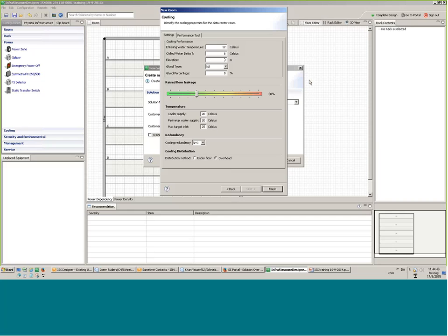So they get derated. It's information to us. The tool itself is not taking care of it. So please tell us it is 1,000 meters or Johannesburg 1,700 or wherever. Glycol type as well. What you have is also derating the water capacity. If you have 30%, it's derating the water capacity.